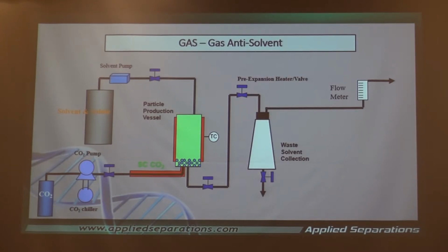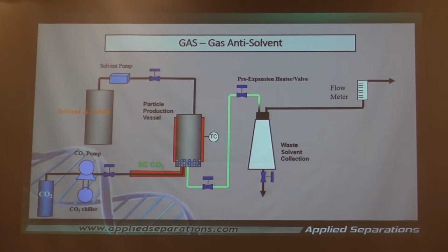You will determine the rate of dissolution of the solvent into the CO2, and then having the solute fall out of solution. Now, I said a lot there. Do you understand that? So once you're done, then you just drain this off, and you have your particles. Now, as you continue the CO2 flow through there, then obviously you're drying it as well. Then we just discard the solvent.